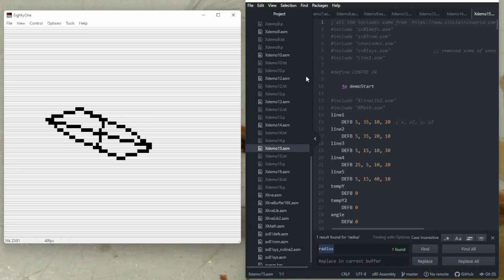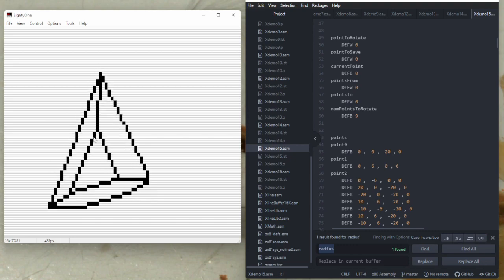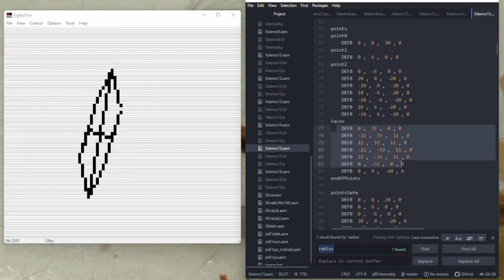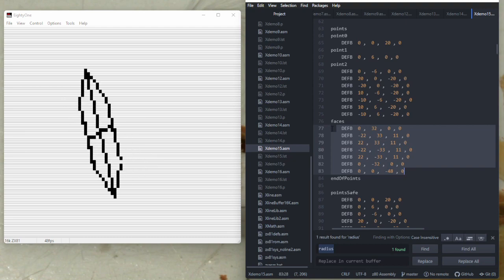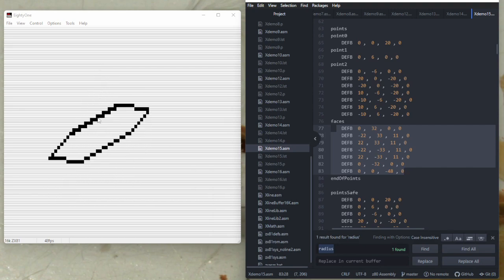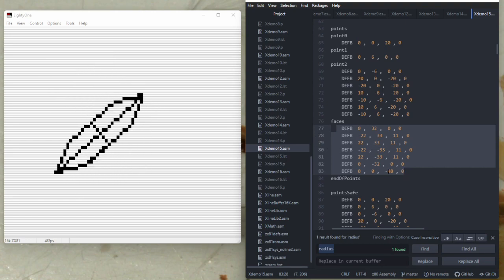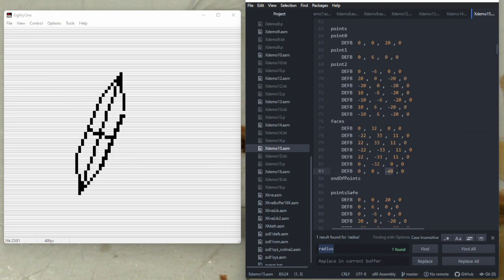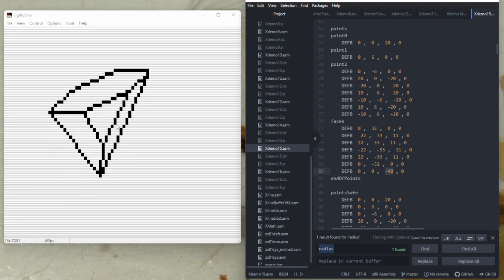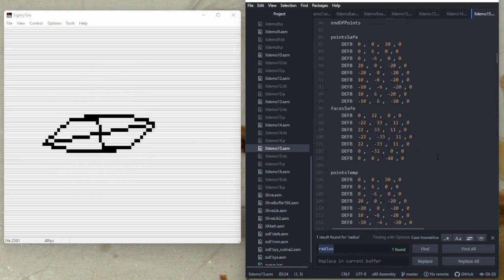And then finally, the one I was kind of pleased with. So this removes the lines you can't see, which it does by introducing a new component, if you like, which is this idea of faces. So these are the normals to the faces. So that's a face there. It will have a normal pointing outwards. And so when that normal is pointing in the negative z direction, like this one is, then that face is hidden. If an edge lies on two hidden faces, then we can't see that edge. So that's the trick here.